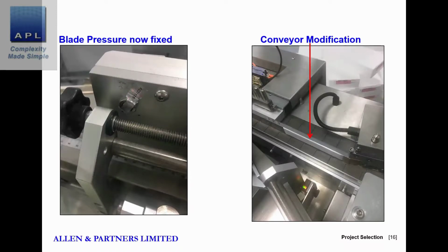So you can see some things here. The conveyor modification, look, is in this photo, and it's simply a PTFE plate that just reduces the friction as the product travels down here. Previously, what they were using was tape, so they were using a temporary solution. It worked, but the tape got in poor condition and they had to keep replacing it. So as it worked, let's make it permanent.